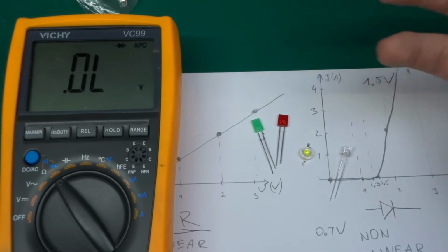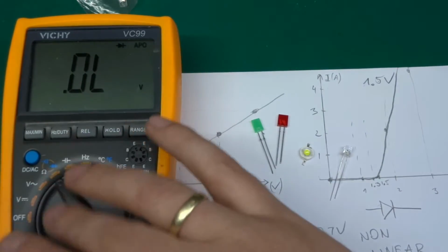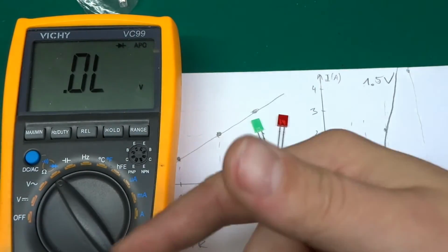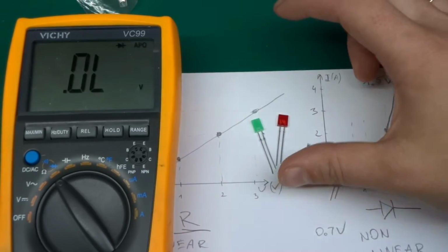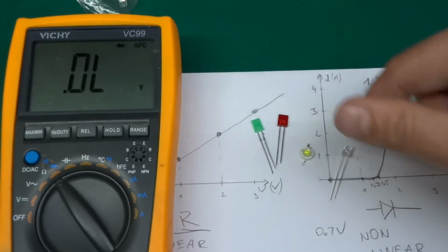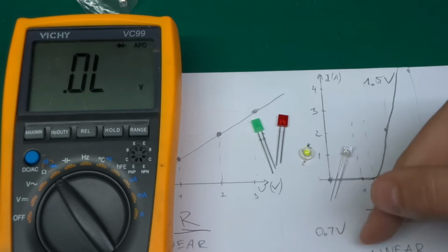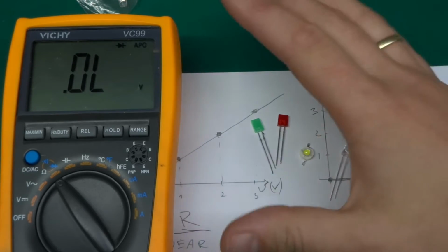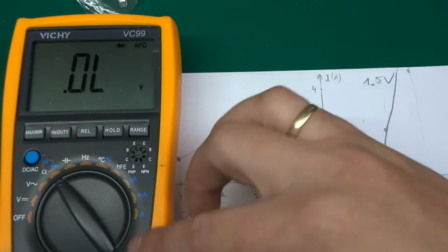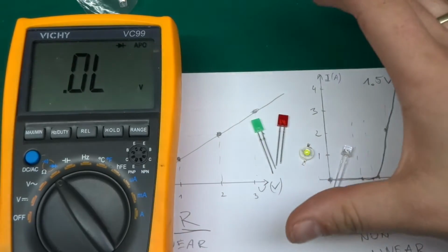They use different voltages. But when you switch over to the diode range, the meter knows you're going to try to measure a diode, so it puts a little bit higher voltage on the terminals because it's expecting that 0.7 to 1.2 volt drop. Typically the multimeter will show up to maybe about 2 volts of voltage drop on a diode.